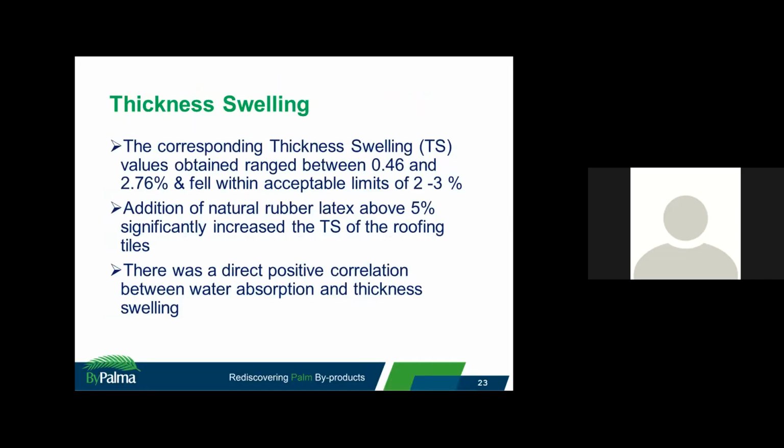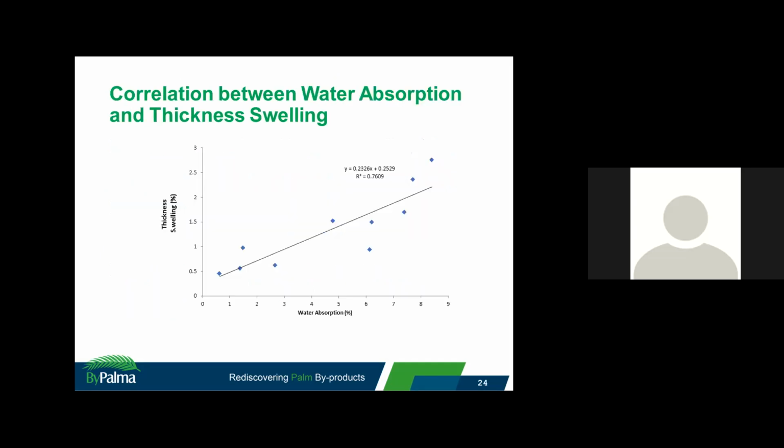And we found a direct positive correlation between water absorption and the thickness swelling, meaning that the more the water that was absorbed, the higher the thickness swelling. That is shown in that figure that we are looking at.